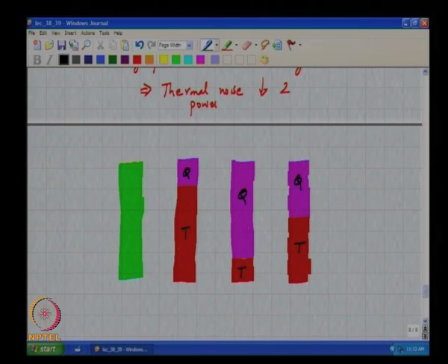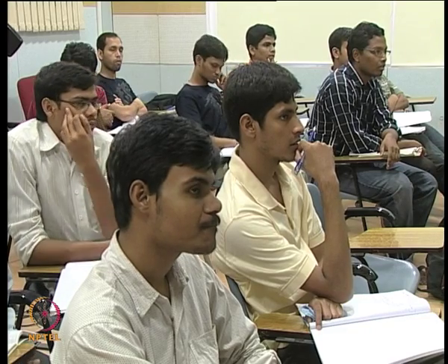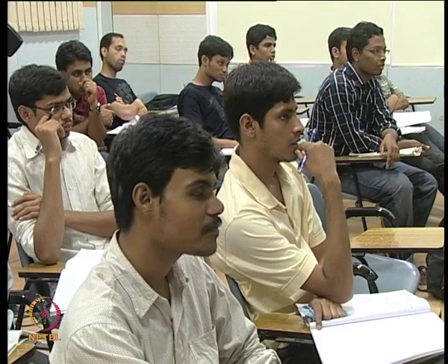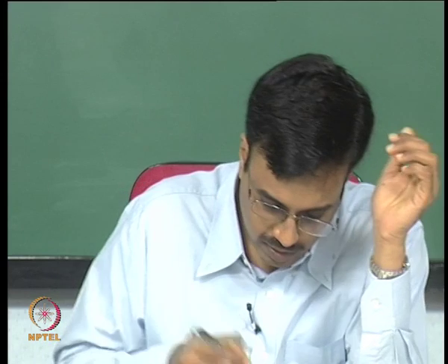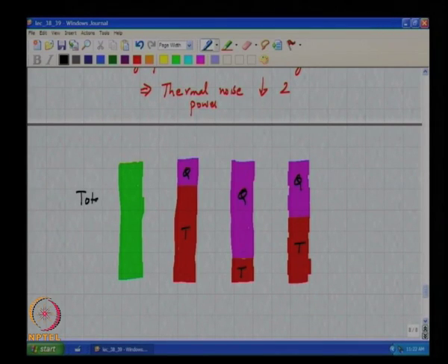So which do you think makes most sense to do? You want more quantization noise and less thermal noise. Why does this make sense? If we have less quantization noise, it means the design of the quantizer is more difficult. Quantization noise depends on overall modulator design. Yes, sure, it is difficult. Okay, so this is the desired total noise.